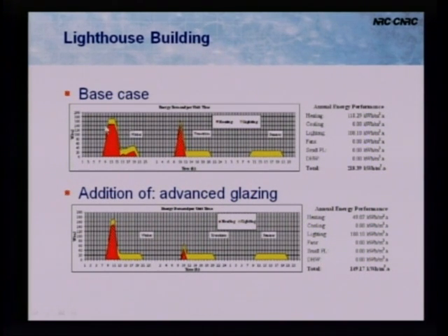different cases. So this is again exactly the same data as you just saw in the previous one. 220 kilowatt hours per metre squared per annum was our initial energy consumption for this building. So we said, well, you've got all this glazing, your heat is pouring out through this glazing, you don't need that much daylight within there, so you can go to, and I think we ended up with some triple glazed, double low-E, argon-filled glazing here with less transmission on it.